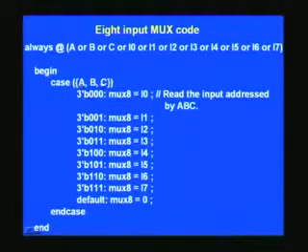That means to say a single signal can be put here, or any other multiple, even a statement can be put here, right? And so what all this means is when ABC, each of them is 0, corresponding to this, what we should get is I0 at the output, right? And similarly, if it changes for different values, let us say 111, naturally I7 must be selected and output to the mux 8. So it is as simple as that. And notice that we have only put one statement here. So occasionally you may have to put multiple statements, in which case, don't fail to put a begin and end towards the end of that statement. And when we go for a demux implementation, which is the exact counterpart of this, then we can see more details on that.